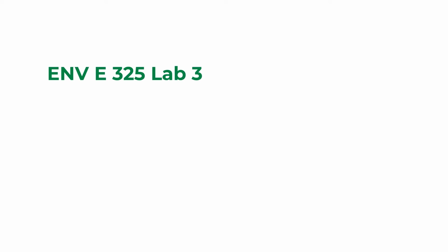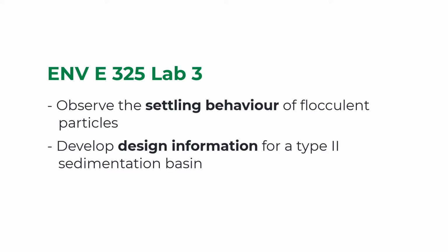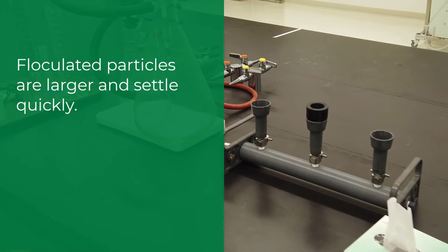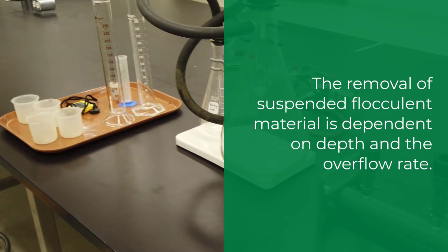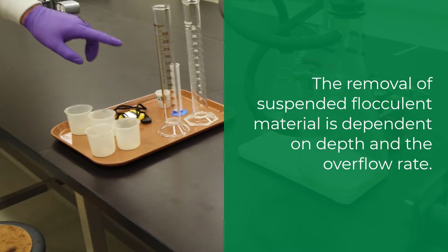Hello everybody. In this lab, our objective is to observe the settling behavior of flocculent particles and develop design information for a Type 2 sedimentation basin. The flocculated particles are larger and settle quickly. The settling velocity of particles becomes a function of depth. Therefore, the removal of suspended flocculent material is dependent on depth as well as overflow rate.